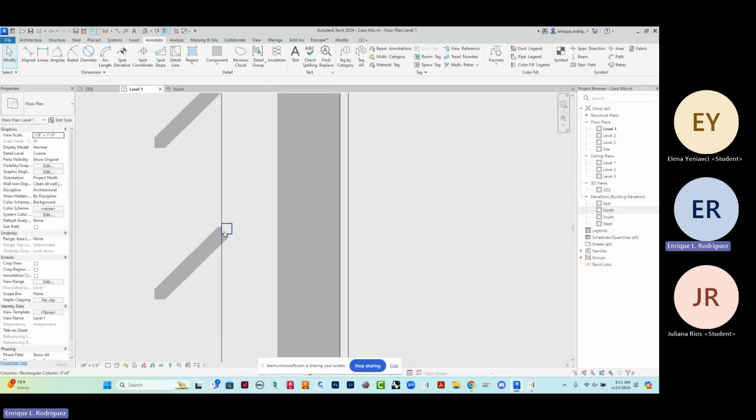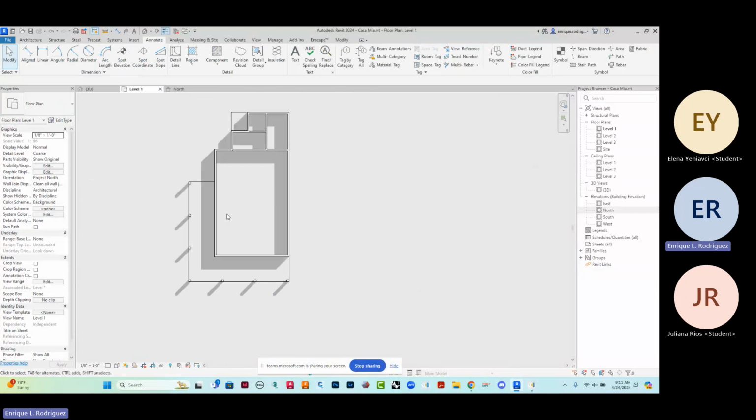We're going to go to the center of the 8-inch column. But it's also going to be determined if we want it the same slope as in the back, which I did at 4 and 12. We just have to make sure that the depth of the porch, when that roof begins to rise from front towards the building, that the top of that roof does not interfere with the windows on the second floor.